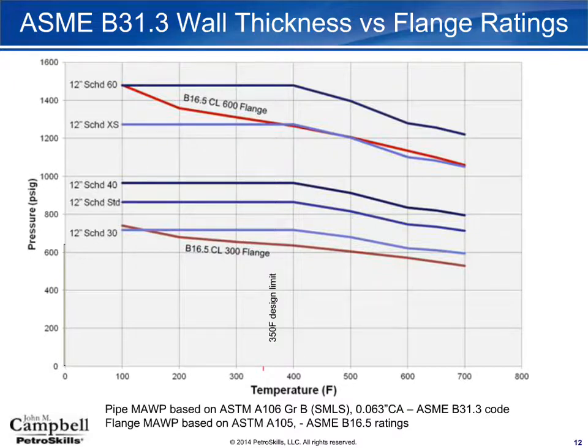And that operating window or design window would be flange limited. If I increase that up to, and I'm not sure why that's not turning out in that animation, if I increase that to the 600 flange, then you can see that the pipe selection for extra strong becomes the limiting component and not the flange. And so this is a key component as we start to analyze pipe wall thicknesses and flange limits, which component is limiting the design.